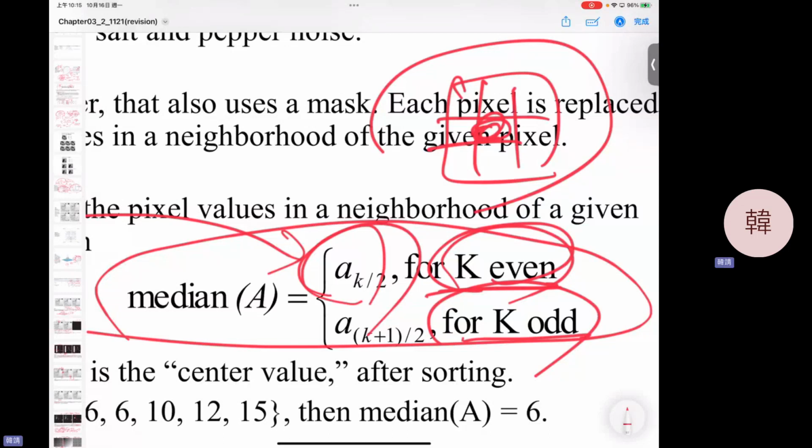So you look at the image, and you know your image is degraded by the white spot or black spot. You can choose maximum filter or minimum filter. Restore your image immediately. However, if you have white and black spots simultaneously appearing on your image, you have to use a maximum plus minimum, or minimum plus maximum, continuously to solve this problem. For sure, you can use median at a time and solve this spike noise immediately. Okay, at the same time.